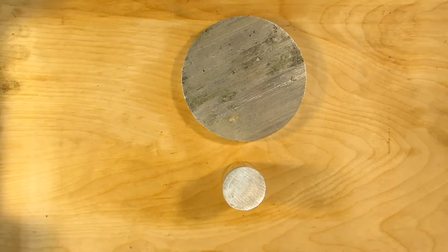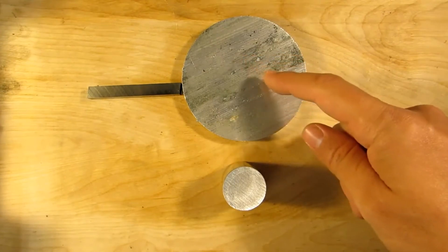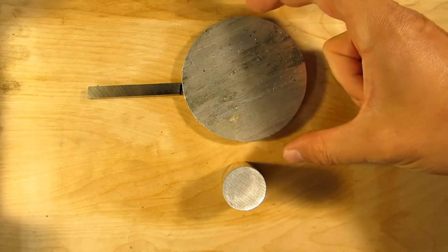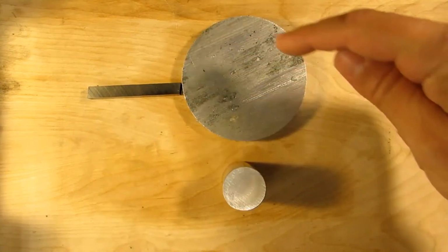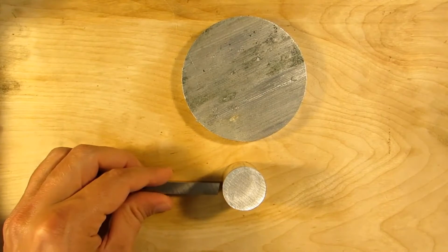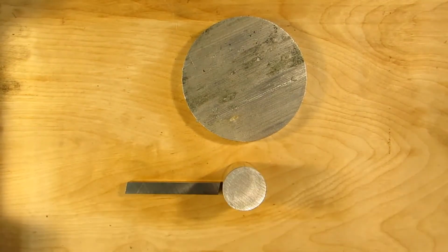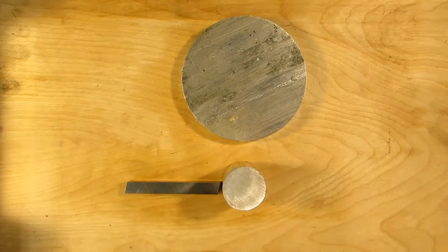past your material. The larger of the two pieces would have to run at a slower RPM because it has a larger circumference, so you have more feet of material moving past the cutter in 1 minute. Whereas our smaller piece, if we put our lathe bit there, would have to move at a faster RPM because you've got less circumference and less surface feet.